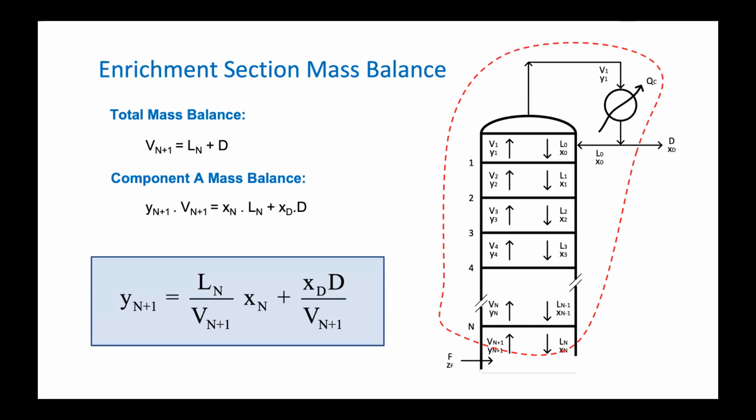So this is the mass balance. We can see the flows from the feed up to here. What we have is the vapor at n+1. The vapor n+1 is the vapor from tray n+1, because the way we write Vn and Ln is the stream leaving the equilibrium stage. For example, this is tray n. The vapor leaving the tray is called Vn, and the liquid leaving the tray is called Ln. The vapor for this one came from the tray just below, so we call it Vn+1.